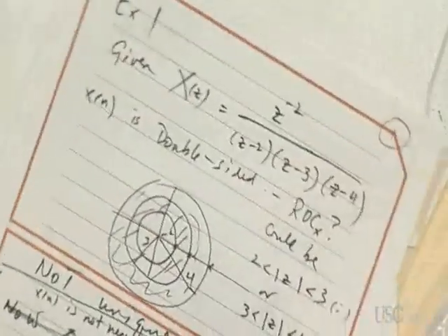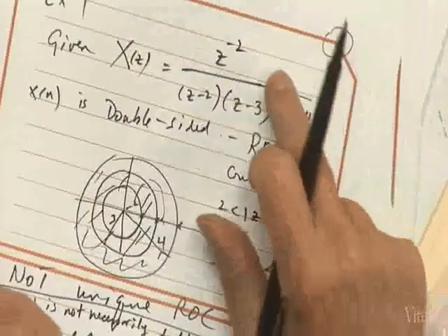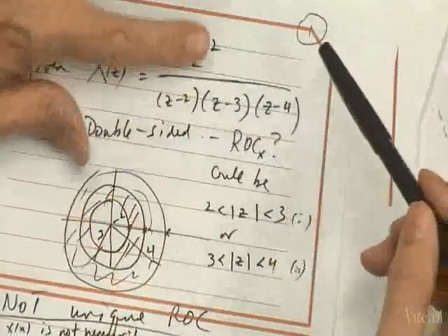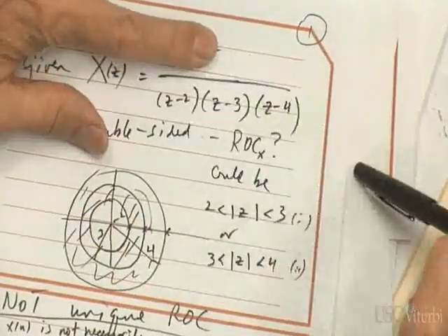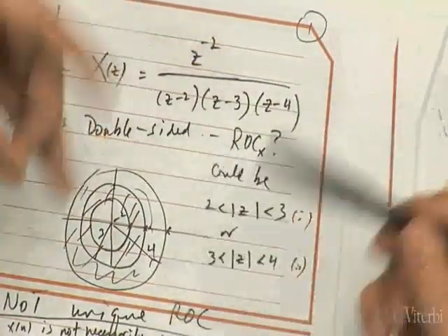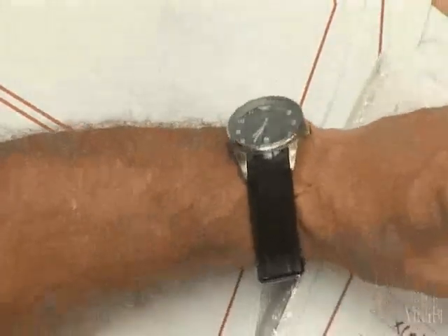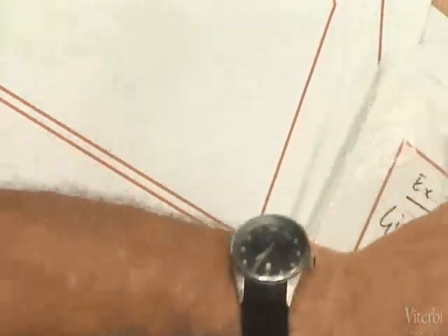Oh, yeah, that's all right. I was just going to say that in this example, there is a power of z to the minus 2, so that you can use the trick I talked about before. You can do a partial fraction expansion of just 1 over this. And then once you've got that and solve for the inverse Z transform, you can just shift it by 2 samples. Okay, but I have another example that I found kind of interesting.